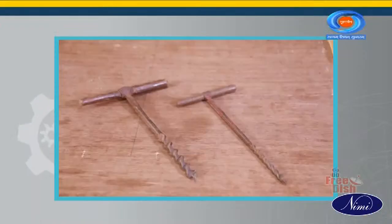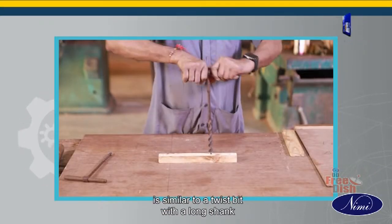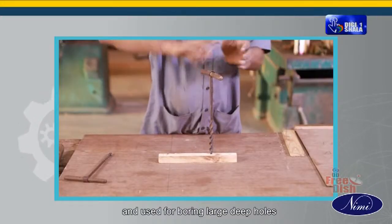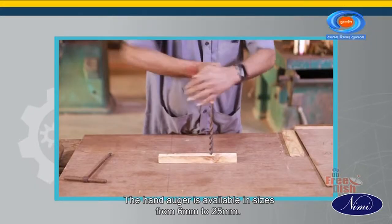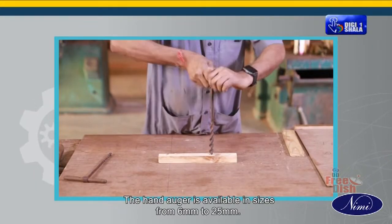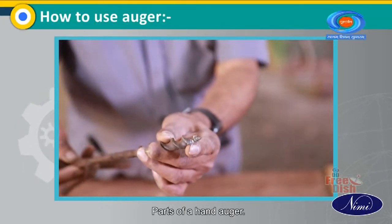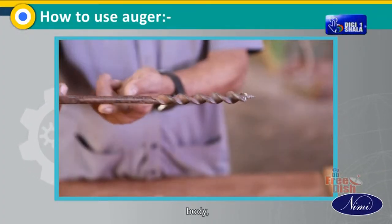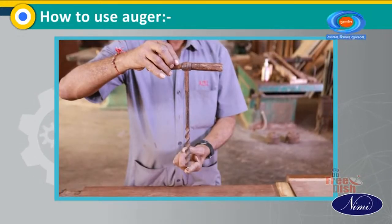Let's start. A hand auger with a twisted shank and threaded point is similar to a twist bit with a long shank and is used for boring large deep holes for poles, etc. in hardwood. The hand auger is available in sizes from 6 mm to 25 mm. Parts of a hand auger: point, shank, eye hole, body, handle. Let's see each of them in detail.